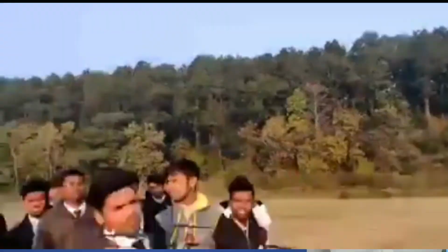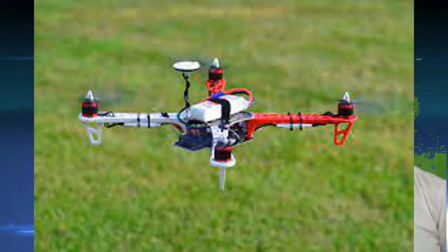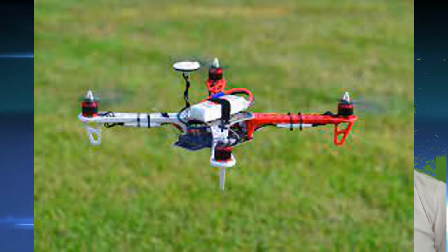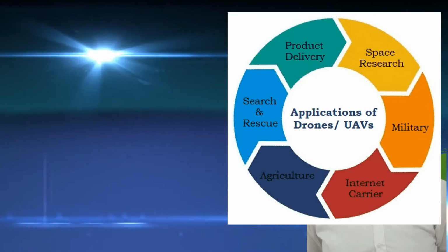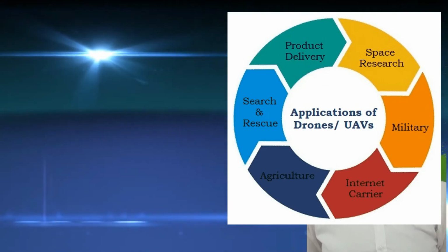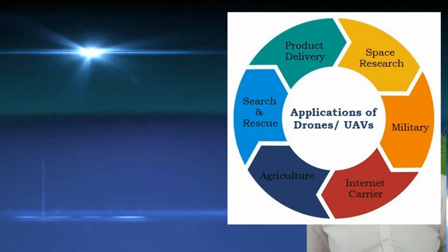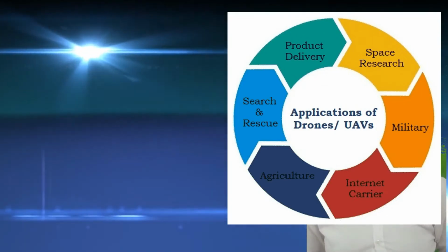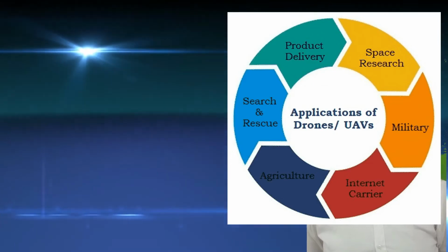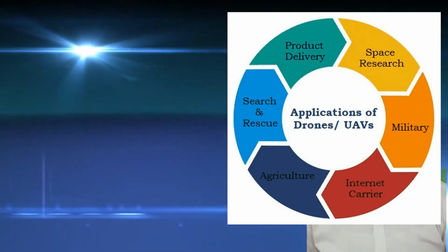Now the question is, what are the disadvantages? Basically, multi-rotor drones have a comparatively complicated structure and programming. They are aerodynamically unstable systems, thus they require an on-board computer flight controller, and have low energy efficiency compared to their fixed wing counterpart.